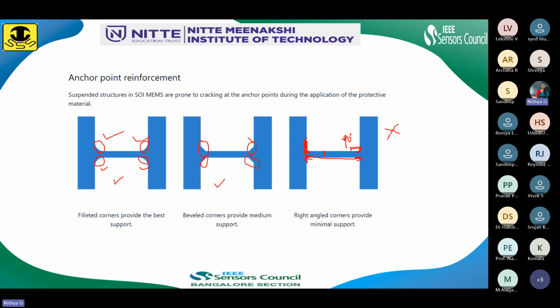Okay, so remember we have to take only three layers for our design. And one more thing, we cannot have more than 100 micrometer length. The constraint is on the width here, because thickness is defined by the thickness of the SOI layer, which is already set as 25 micrometer.